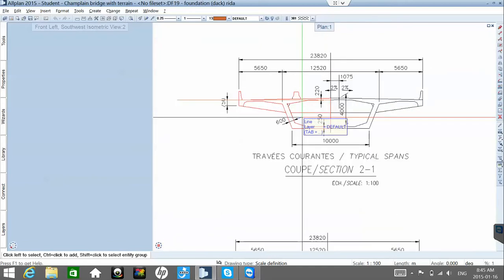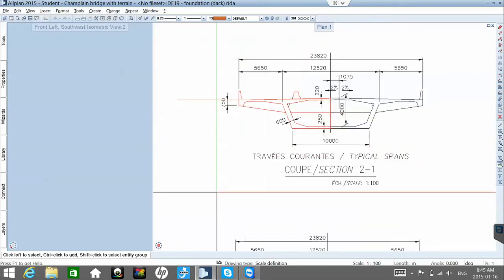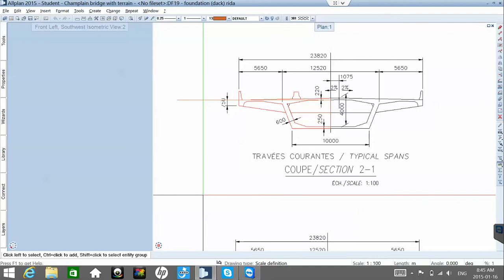This one. Well, as far as I see, it's a portion that is poured afterwards. So this type of structures have precast elements and cast on site elements. So basically this extra line is something that is poured once the prefabricated element is placed in position. So this can be, but let's test it with the cross section you did. I think it will work.